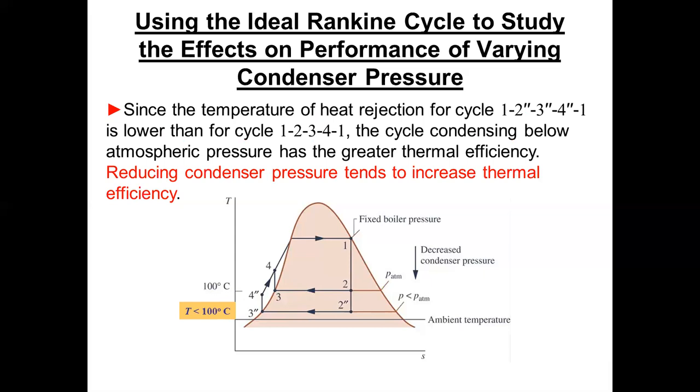Well, anyway, it's not going to come back to, oh, there it is. Okay, so we see the average temperature during the condensing process. It's this level, which is much less than 100 for the modified cycle with a low condenser pressure, and it's up here. So obviously the average temperature, I mean, that looks like they're constant temperatures, so it would be easy to do the average. It's just this compared to this is going to be lower in this case.